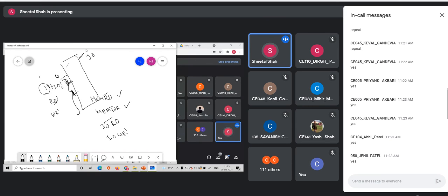Say suppose this pin is read bar, and that is 0. Read bar, it is bar. That means it is an IO read bar operation. Similarly, if it is 001, 010, in that case it would be IO write bar, and so on. Whereas if this pin is 1, then accordingly it would be memory read bar as well as memory write bar. Hope everyone is clear with this.